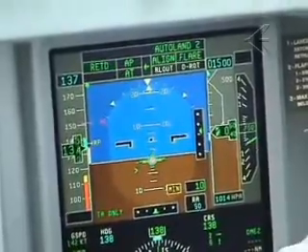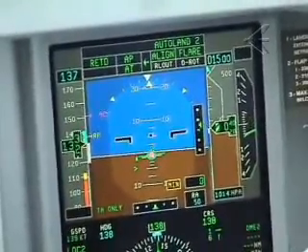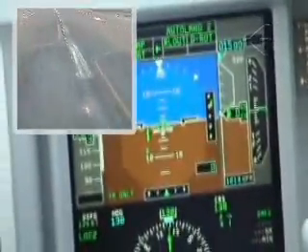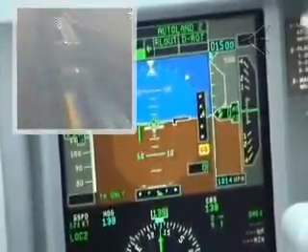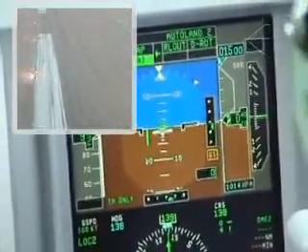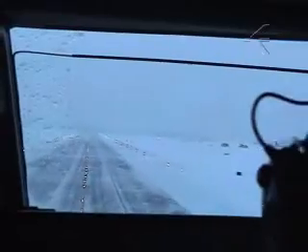At main gear touchdown, rollout and derotation modes engage. Check that centerline is maintained while the nose is lowered to the runway. Check also that autothrottle disengages normally. The Autoland should perform reasonably. It should land in the touchdown zone.